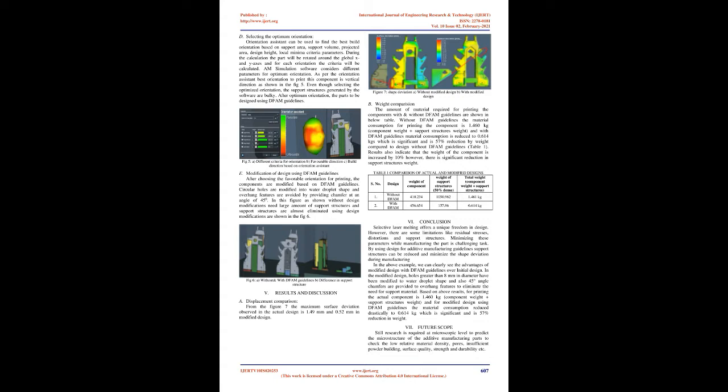The result is a design in which support material is only necessary to attach the bottom of the part to the build plate. Using DfAM guidelines, the part geometry can change slightly and again extra post-processing is required. However, using DfAM guidelines, time taken for printing the components, support structures, material required for the component billeting and processing cost can be reduced.